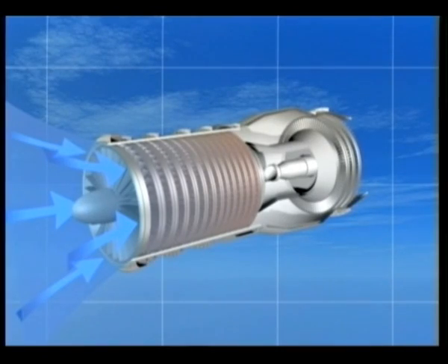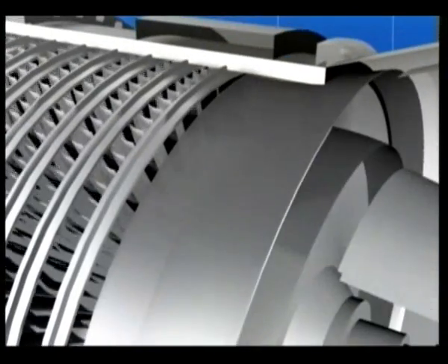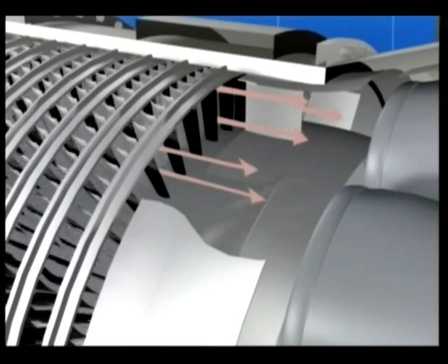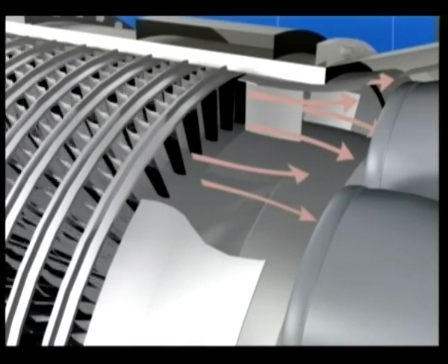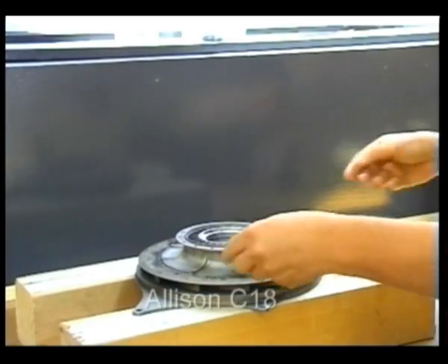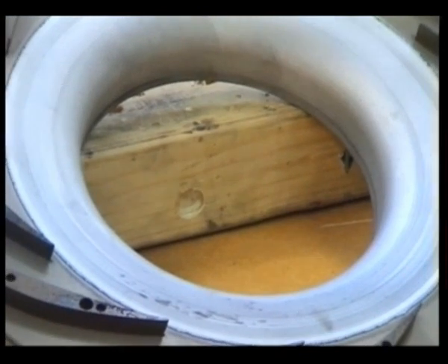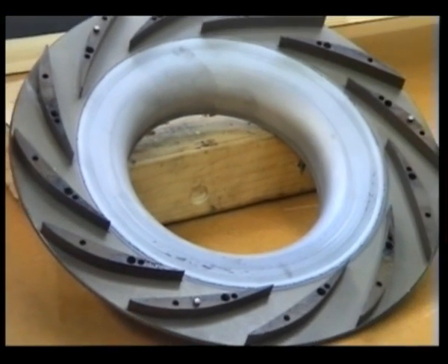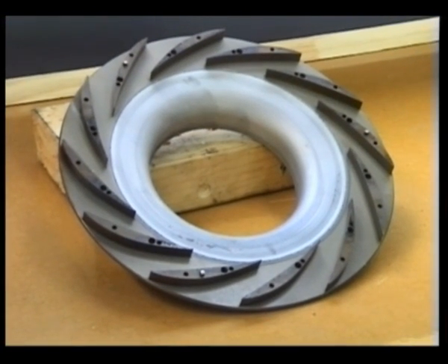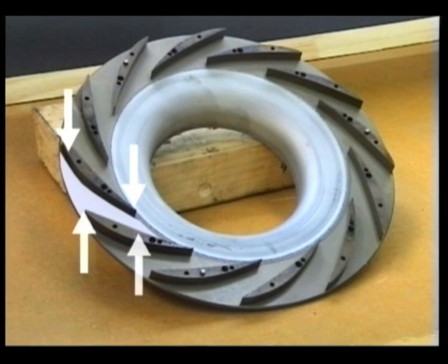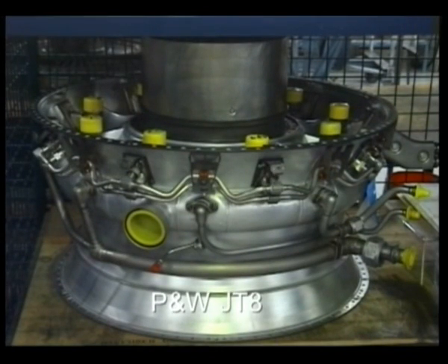At the very exit of the compressor, a diffuser section within the engine adds the final touch to the compression process by again decreasing the velocity and increasing the static pressure just before the air enters the combustion section of the engine. The theory being that for a continuous flow process, that is, when under steady conditions the same amount of gas passes all points in a given time, the flow is led through a divergent passage which causes a drop in velocity with corresponding increase in pressure, density and temperature. Diffusers are made from aluminium alloy or steel, depending on operating temperatures.